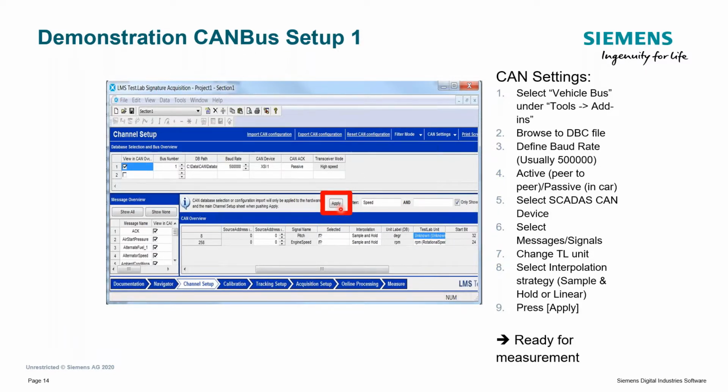All right, so what I did there was I recorded the RPM along with my analog channels. So pretty straightforward. One of the things about these digital signals, unlike an analog signal, is if you have problems, because it's digital, it's like an all or nothing. If I don't see the engine RPM, if it's just reading zero, it's not like you can go in and fiddle with a tachometer.